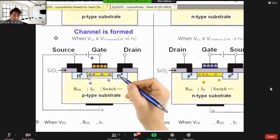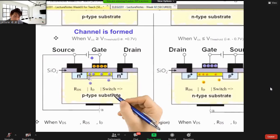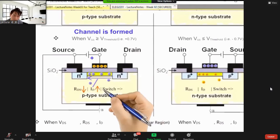Okay, how about the other one? Bottom left, when the VGS is greater than or equal to V threshold, the channel is formed. When the channel is formed, let's see. When I connect the source to the substrate or to the ground as well, because the channel is formed, the RDS is not infinite anymore. So we have the ID, but the ID is increasing.